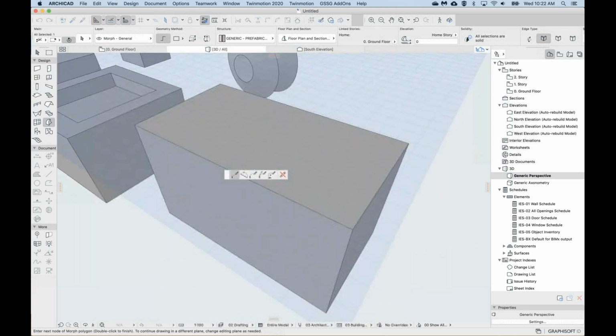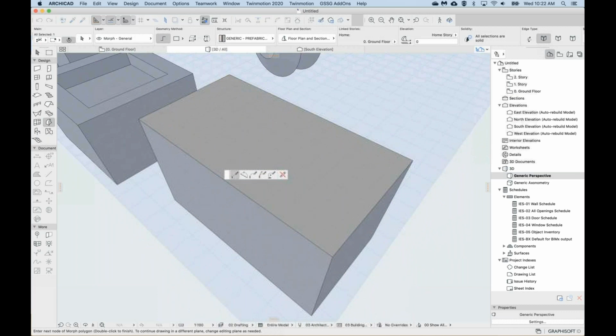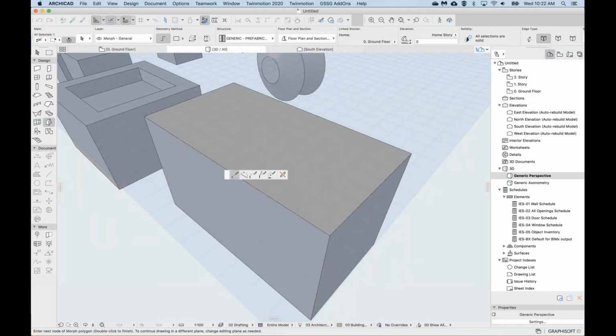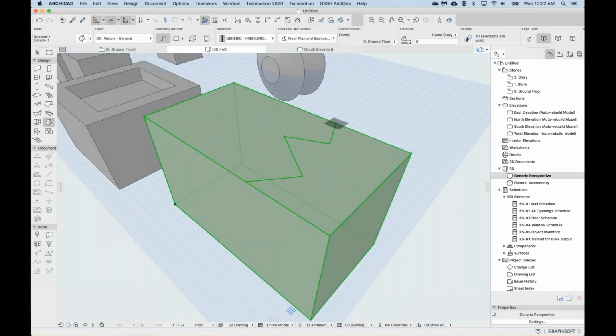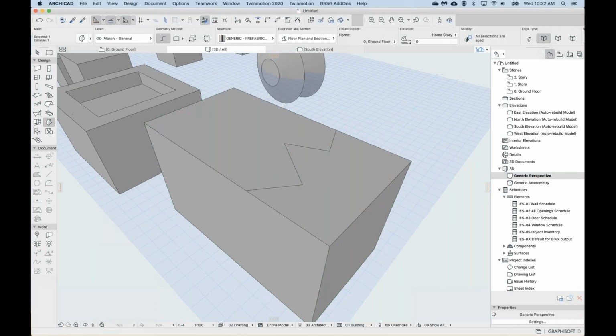You may have to move your camera around because it may try to snap to edges in the background, so be careful you're drawing only on this top surface. Then I'm going to hover over the line on the other side, find the endpoint, and then find the third point. When I find this on the opposite edge, I click, which completes this polyline.